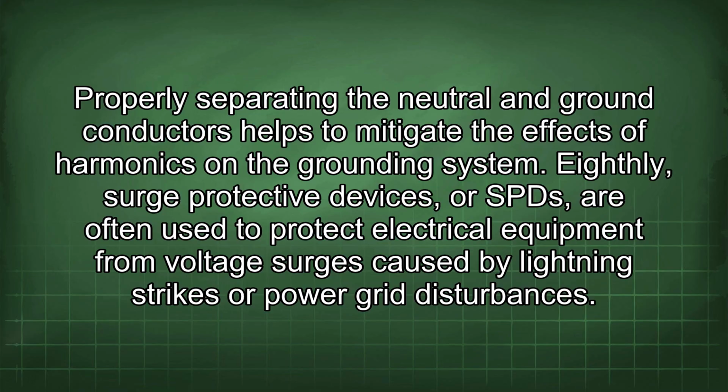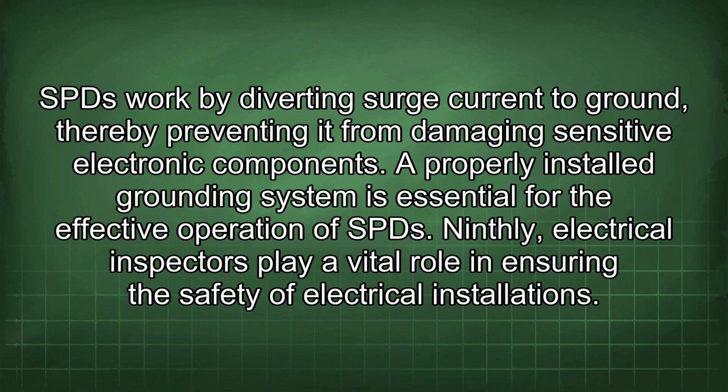Eighthly, surge protective devices, or SPDs, are often used to protect electrical equipment from voltage surges caused by lightning strikes or power grid disturbances. SPDs work by diverting surge current to ground, thereby preventing it from damaging sensitive electronic components. A properly installed grounding system is essential for the effective operation of SPDs.